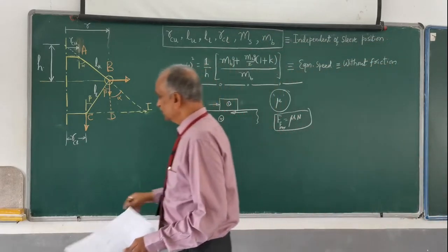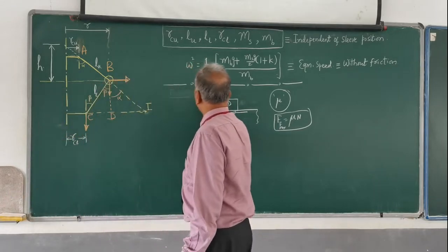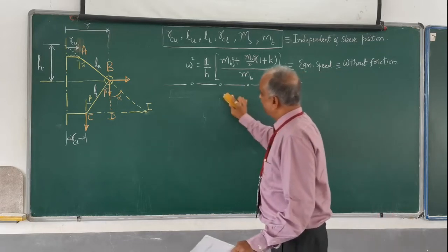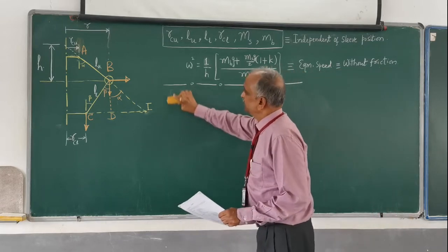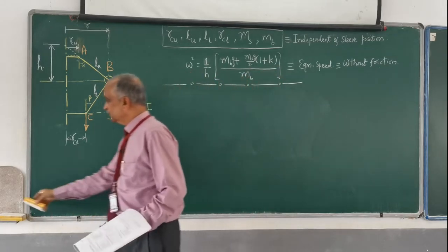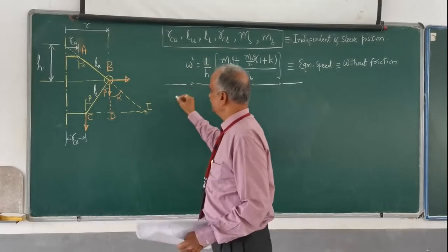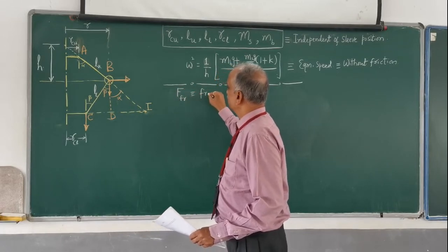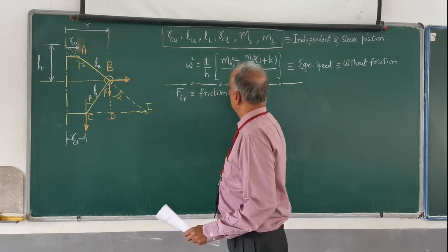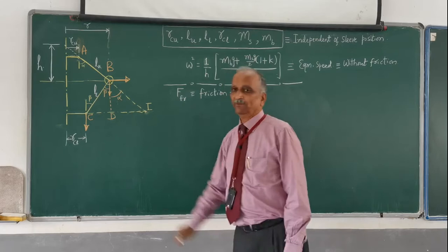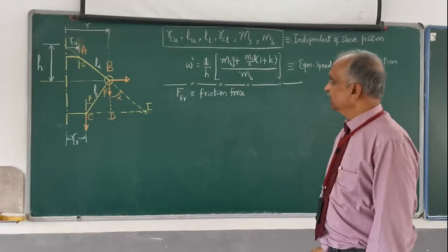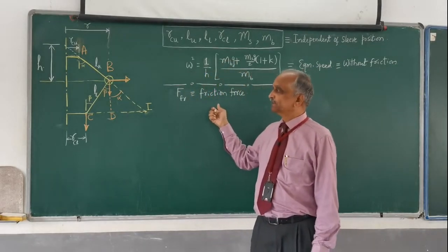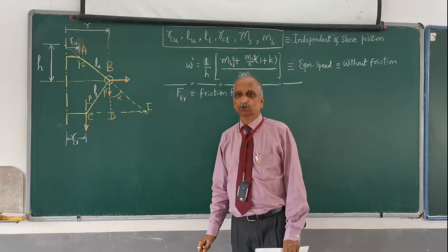Okay, so let me make use of this concept now in our analysis. Only if I overcome that friction force will it start moving. Now I would like to take the friction force. Let Fr be the maximum friction force between the sleeve and the spindle. Now, what is the direction of this friction force? That depends upon in what direction the sleeve wants to move.